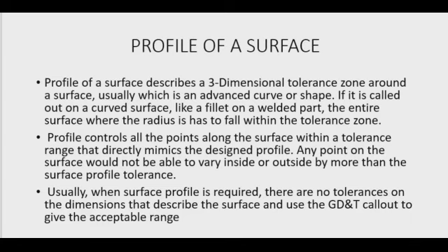Usually when a profile of a surface is required, there is no tolerance on the dimension that describes the surface, and GD&T is called out for an acceptable range.